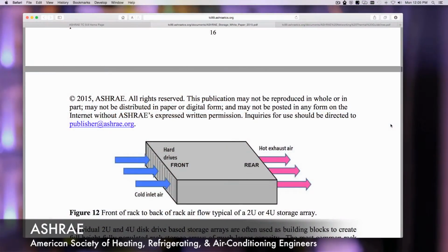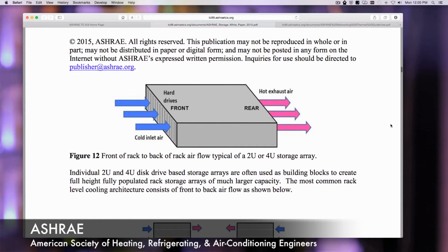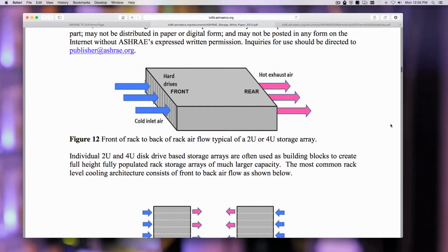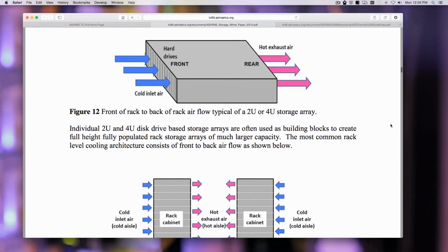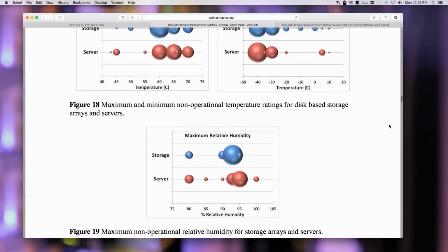One of the principal changes that has allowed this technology to become viable is the opening up of the environmental conditions within the data hall itself. There is a standard published by ASHRAE, TC 9.9, which recommends conditions for air entering the server. Over time, ASHRAE has been increasing the allowable temperature at the inlet to the server. They've been doing a lot of work with the server vendors, expanding that envelope, increasing the supply temperatures and expanding the humidity range, which really allows the engineers to adopt different technologies and make them more efficient.